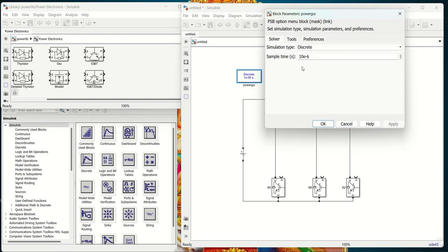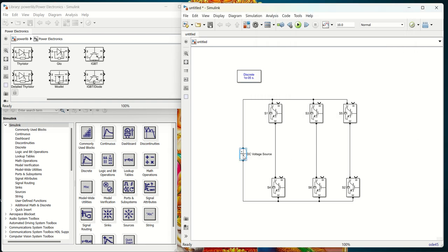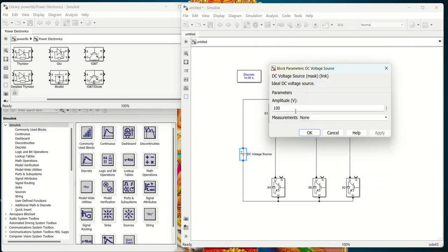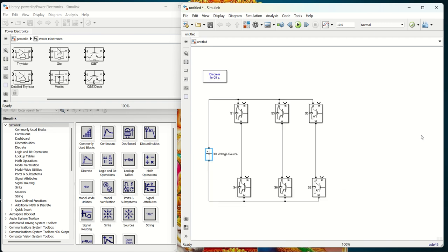The lower your sampling time, the better your response will be; it will be a very good response. In some digital applications, the sampling time may not support up to 10 microseconds. Then you can go for 20, 40, like that. In general, since it is a three phase, the minimum voltage we are going to maintain is 600 volts, in order to get a 415 volt output.